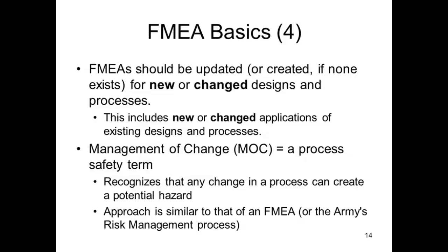For example, I get the American Institute of Chemical Engineers magazine, and they have these safety case studies. There was one where they emptied an oil tank, purged the lines with steam, and then apparently some of the steam condensed in the pipes. They put hot oil in, which expanded the water and blew the tank open, and caused some serious damage. But that's an example of a change.